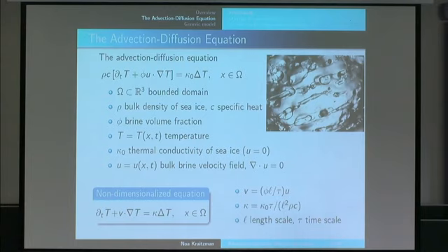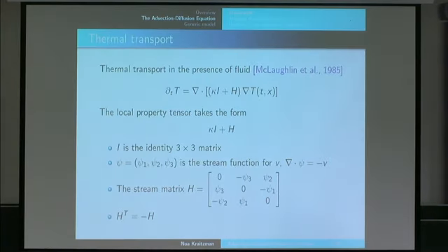Now, just because I am doing math, we're trying to ride on the nice balance between a physical model and an easy-to-solve model. So we're going to non-dimensionalize the system just to make the analysis easier. So we're using the characteristic length scale and time scale of the system and just rewrite it non-dimensional. If we rewrite the advective term as a diffusion term, we can actually reduce this equation into a diffusion term in the temperature, in T.